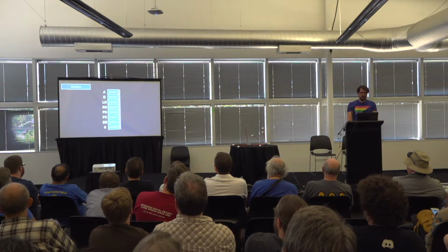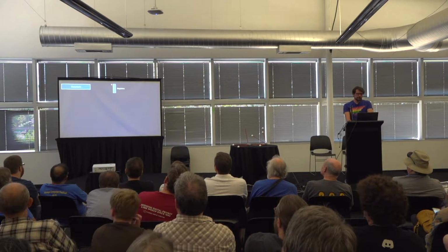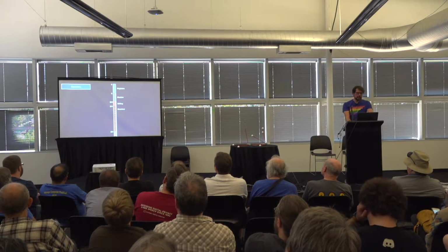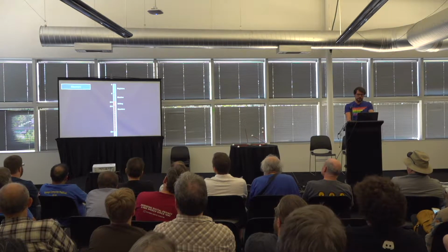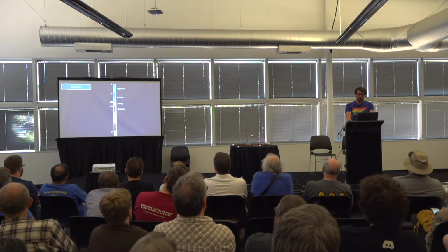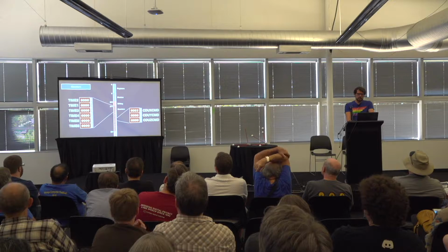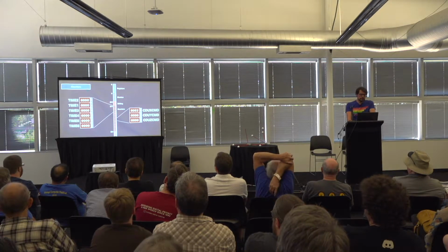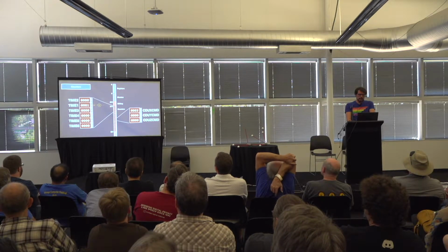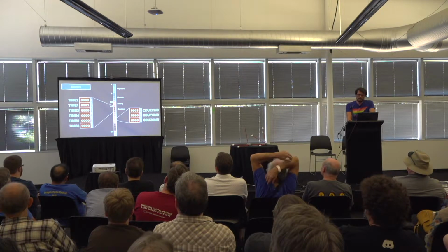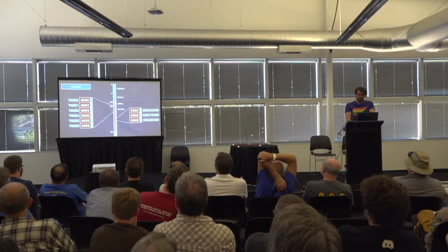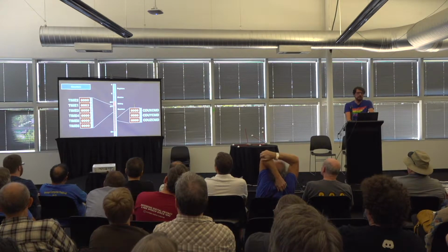So after the registers, the shadow area, and the editing registers, there's another special area, the counters. Like I/O channels, they connect to external devices, but they don't send bits or whole words back and forth. Instead, they are controlled by hardware pulses or cause hardware pulses. On every pulse, timer 1 gets incremented, for example, while other counters take the number stored into them by code and count down, generating pulses.